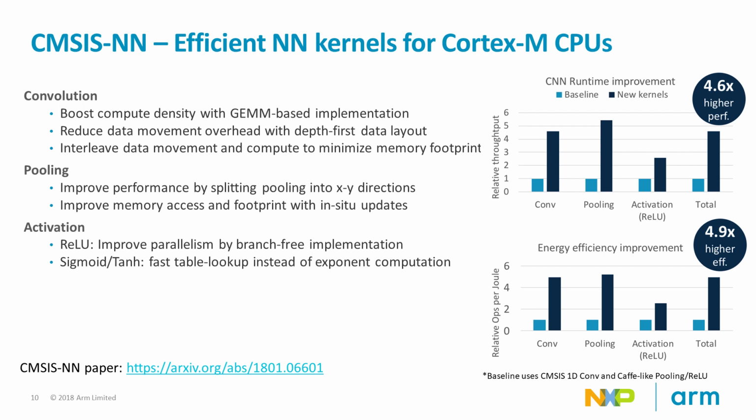Where do these improvements come from? Let's look at the keyword spotting example that we run in a minute and see how much performance CMSIS-NN gains on this and how it does this. The default implementation that will run on a model from an NN framework for audio data will typically use a 32-bit float data type for the input data. This is where the gain using the FPU offered by the processor already comes into play.